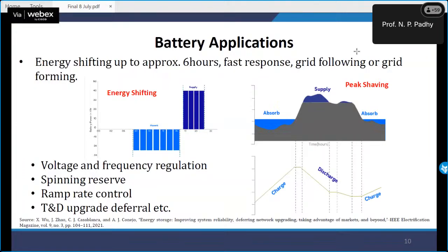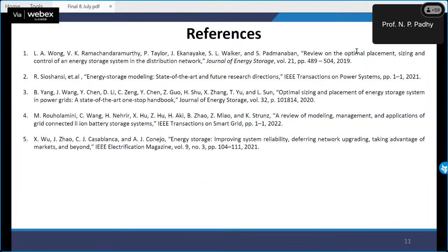So we say the frequency regulation can be managed by an additional source such as batteries, which can be used to discharge during a sudden increase in load, or any load changes. Whenever there is an increase in load, your battery can immediately discharge to maintain the frequency constant or at the desired value. Good. So I think this is all about today's lecture.